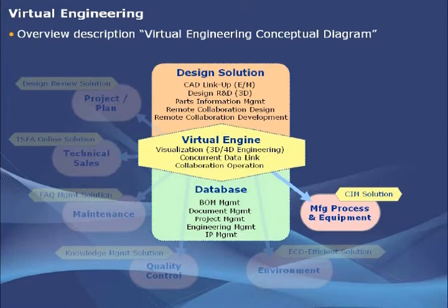For example, wire bonded data can be read into the system and build an intelligent database of loop profiles. Then, the 3D/4D simulation can run completely on actual manufacturing data, and the system can generate files that are optimized for a specific design in the language of the wire bonder. The data files can be plugged back into the wire bonder, and the wire bonder is ready to start with no extra teaching necessary.